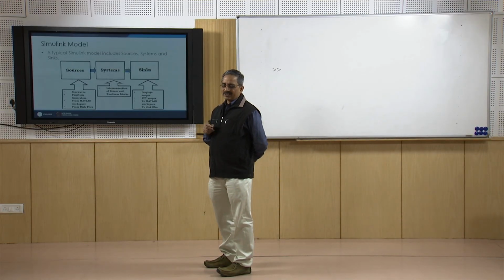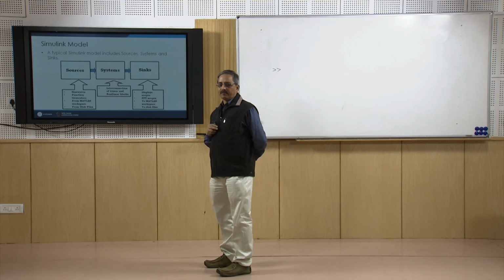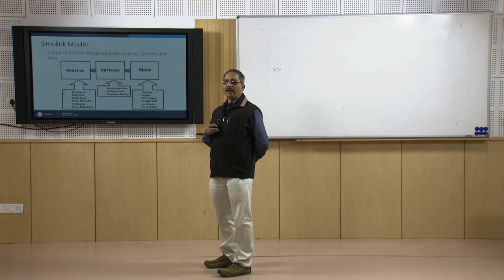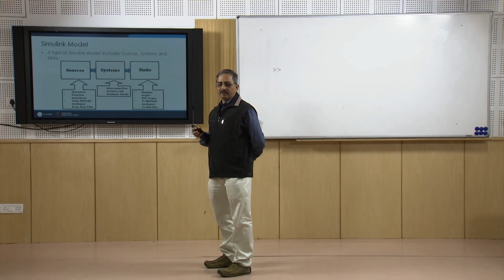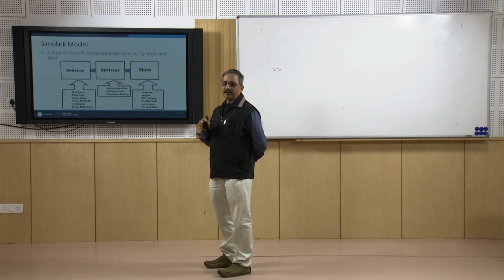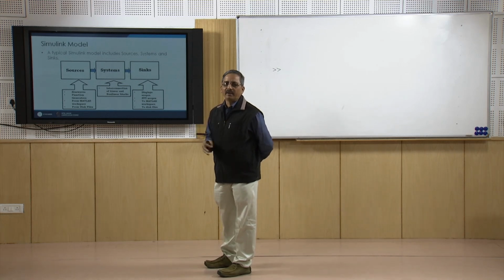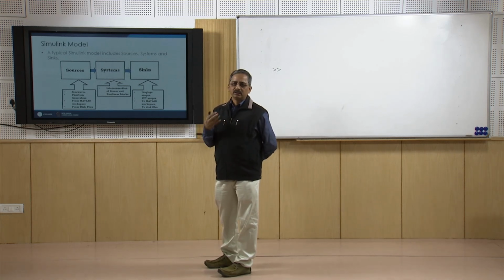Broadly speaking, we have the sources where we can incorporate different types of sources in the model. We have the sink where you can visualize your output, and in between the sources and sink you can have system blocks, where you can use the linear and non-linear blocks available in order to create your Simulink model.